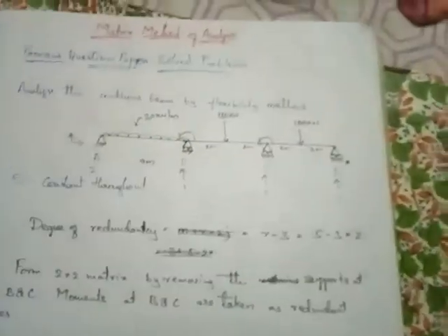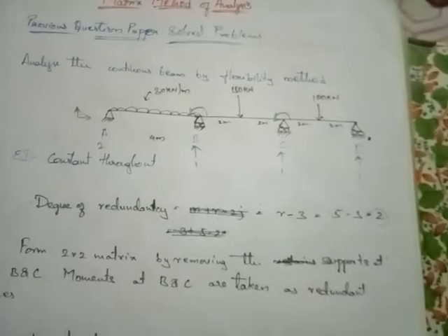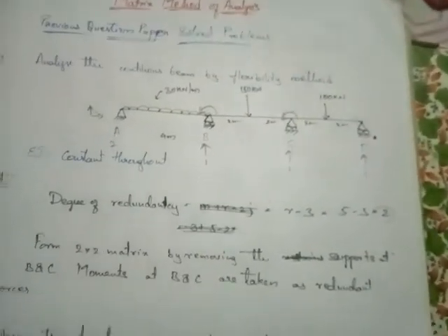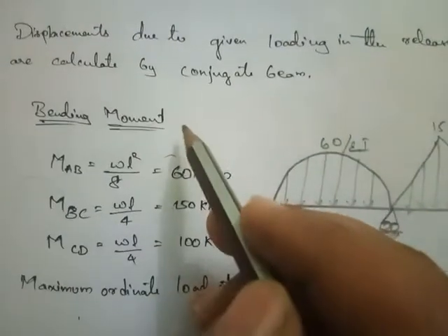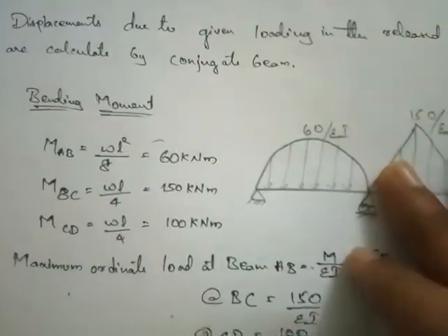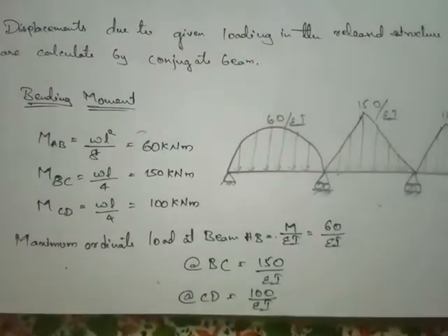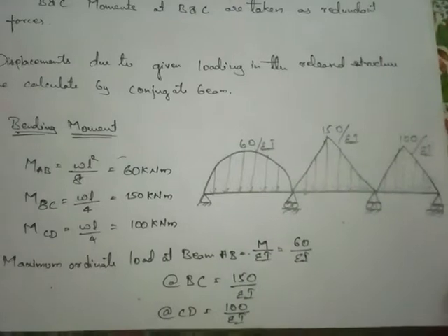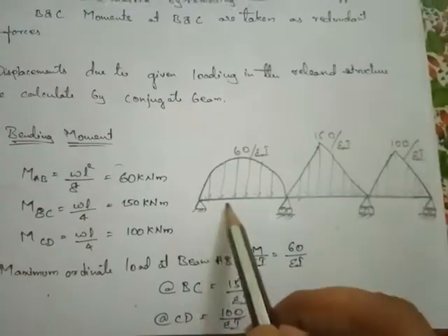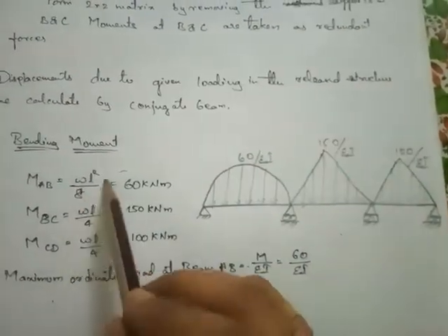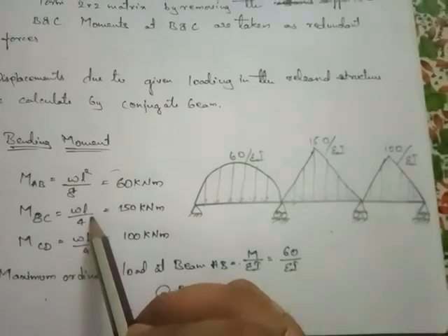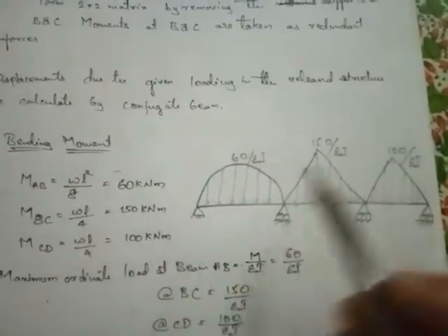So as you have released these frames, before we go for that, we are supposed to analyze the bending moment. Okay, as you know, the second step that we are doing here is to analyze the bending moment using the formulas. As you know, the formulas are, for UDL it is WL square by 8, for point load at center it is WL by 4.